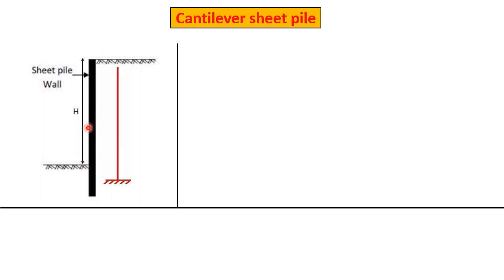And in this type of flexible retaining walls, you don't have to check sliding, you don't have to check overturning or whatever. So the typical geotechnical designs that we made last week, you don't need to satisfy these requirements here.